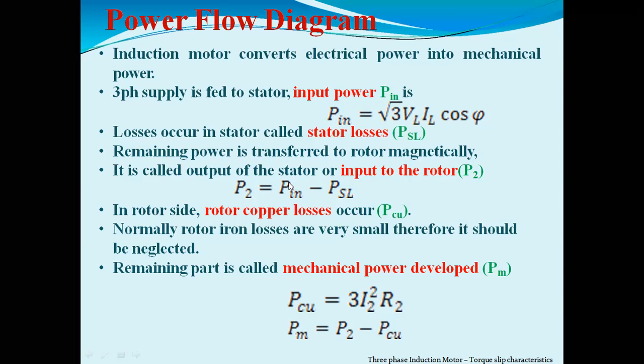It gets divided into two parts. How is it dividing? Some part is going to the rotor, and some part is going to the stator loss. So we can write this equation. When we use the three-phase induction motor, there will be rotor copper loss. Normally rotor iron losses are very small, so we can neglect that.